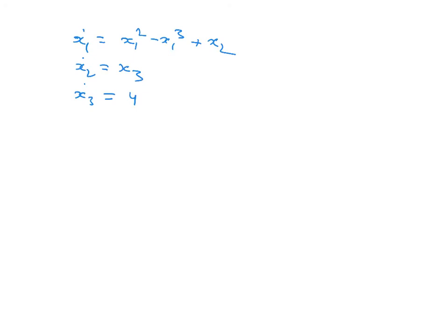So now your u appears in the third term, right? It's like you're controlling the jerk instead of acceleration, right? So position, acceleration. So your input is jerk now. So how do you control the jerk such that both position and velocity go to the desired values? That's a very, very powerful tool, if you will, from that perspective, right?